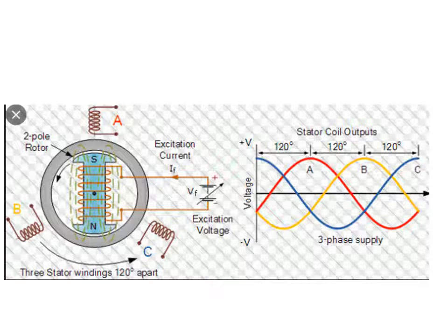In the theory of three-phase AC circuits, we represented them as RYB, red, yellow, blue. Here it is the same thing, A, B, C. They are different sets of windings, placed in such a way that the EMFs generated in these conductors are 120 degrees out of phase with each other. So the three stator windings are 120 degrees apart, and this is a stationary part.